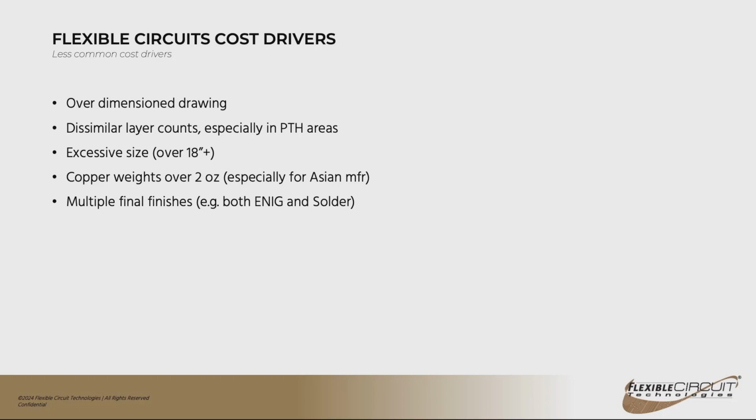Material, it depends on where you're getting your material from. Some manufacturers will supply the material in 24 by 36 inch sheets, and a lot of the Asian suppliers will supply it in rolls that are anywhere from 250 to 500 millimeters wide and then continuous length. And so it kind of depends on where your circuit is being manufactured on what those standard panel sizes are.